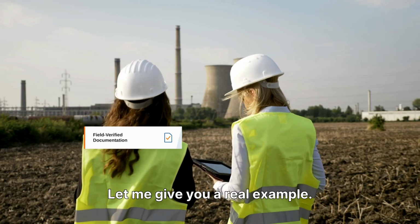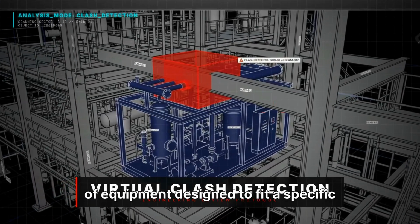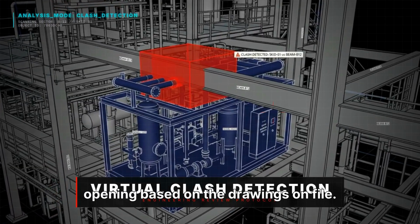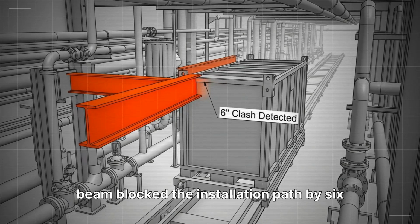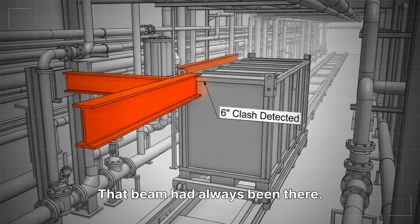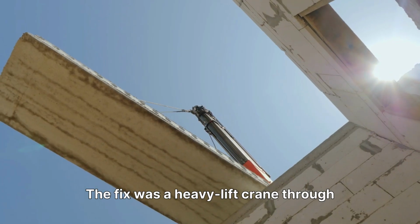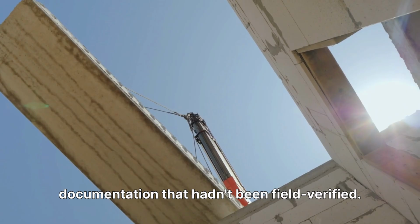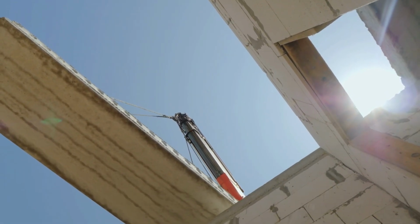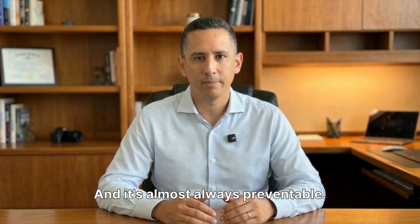Let me give you a real example. A processing plant purchased a custom-built piece of equipment designed to fit a specific opening based on the drawings on file. When it arrived on site, a structural beam blocked the installation path by 6 inches. That beam had always been there. It just wasn't in the drawings. The fix was a heavy lift crane through the roof. The cause was design decisions made on documentation that hadn't been field verified. That's not a unique story. It plays out on brownfield projects everywhere, and it's almost always preventable.